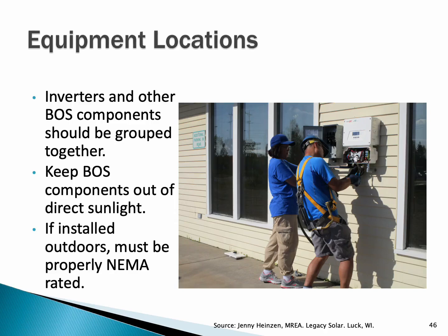And if I put it outside, even though our equipment is rated for being outside, like the inverters and disconnects, then it has greater swings of temperature, as low as minus 25 degrees to all the way up to 100 degrees Fahrenheit. And if it's in the sunlight, it's going to be even hotter on the south side of the building.